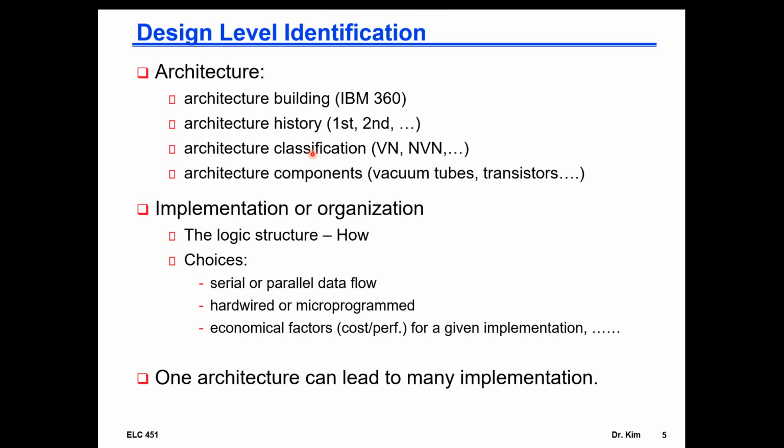You have a dedicated bus for the interface between the processor and the code memory, and you have a separate interface for the memory that holds the data. That's called a Harvard organization. It's better because you don't have to share the bus, but it costs you to have a second bus. So that's a trade-off.